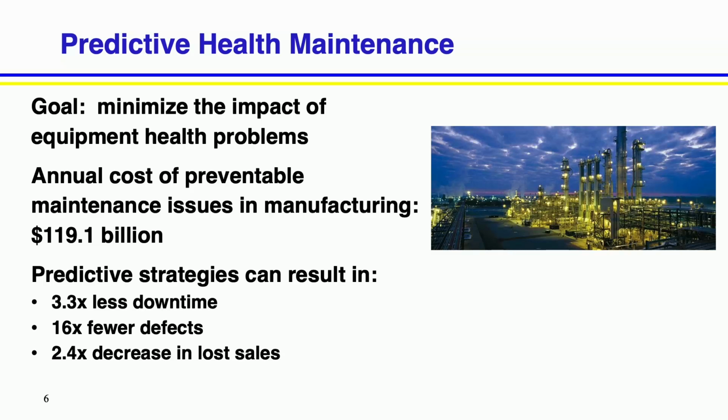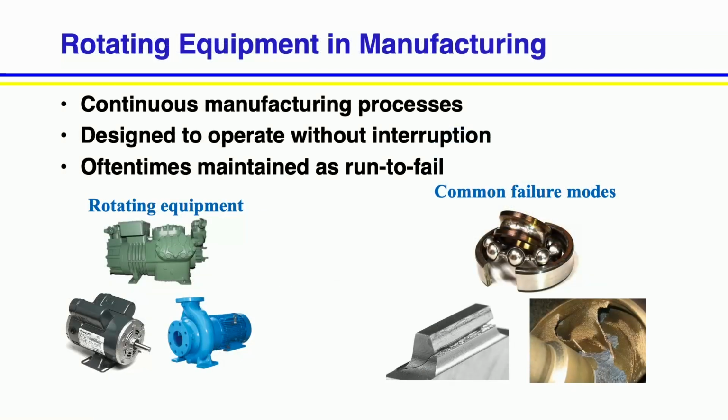And so there's a lot of opportunity you can see in predictive strategies, but why don't people do it more often? Well, the answer is it's hard to predict things, especially when there's a lot of uncertainty in the system. There is a lot of data available that you could say, well, let's put a machine learning model on it. However, because these systems fail so infrequently, almost all of the data is when the system is healthy. So you don't have a lot of those failure examples to train your machine learning model. So what can we do with mostly data that's good?